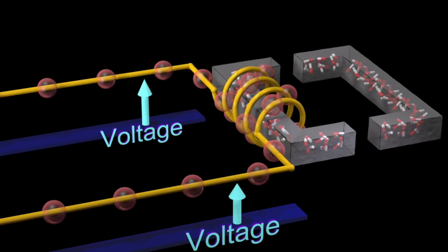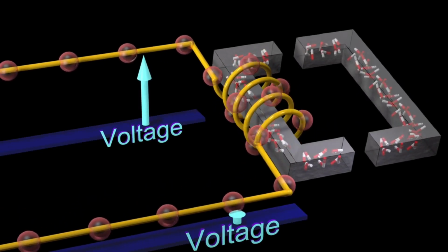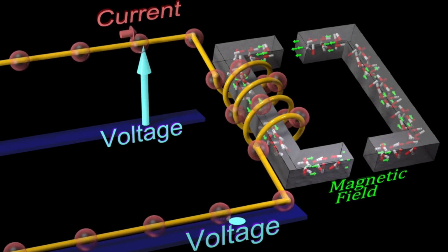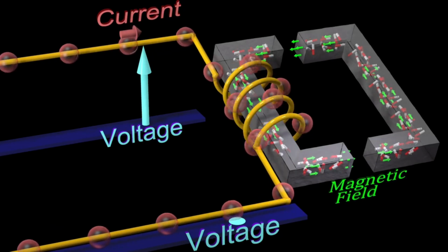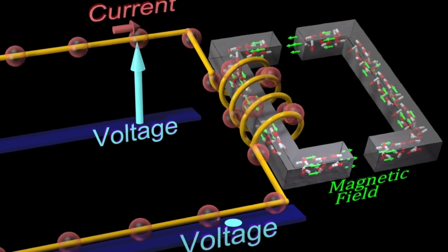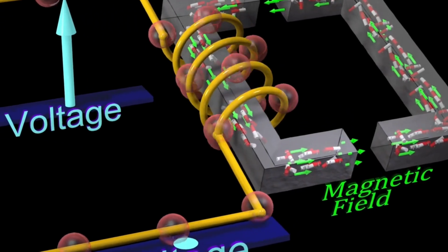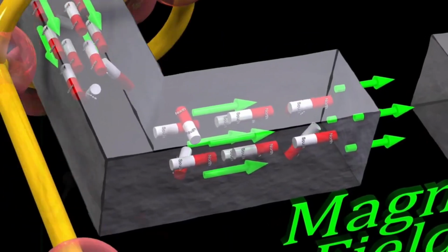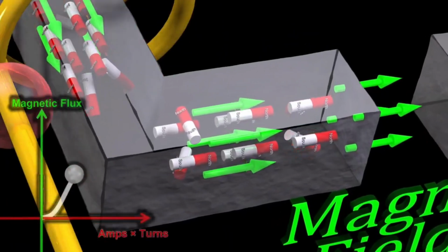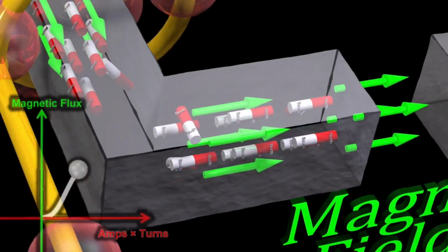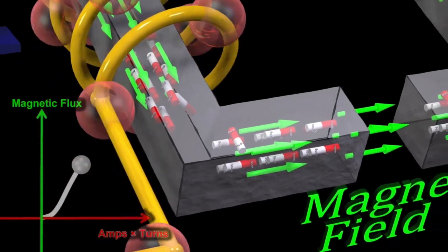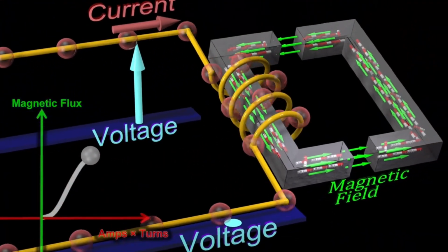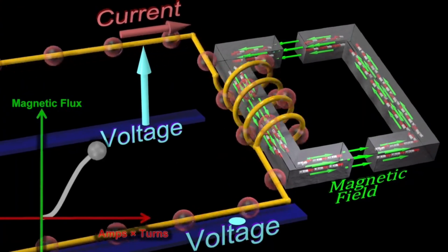If we apply a voltage difference across a coil, a current will flow, creating a magnetic field. A magnetic material can be thought of as containing many miniature magnets that align with the field created by the coil, thereby strengthening the magnetic field. After 100% of the magnets are already aligned, increasing the magnetic field even further involves much greater increases to the current.